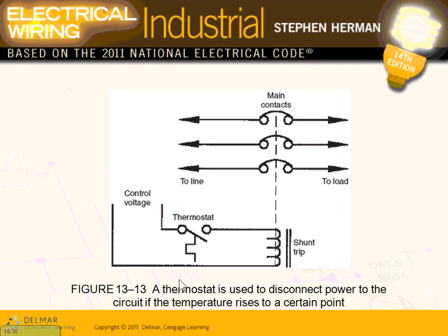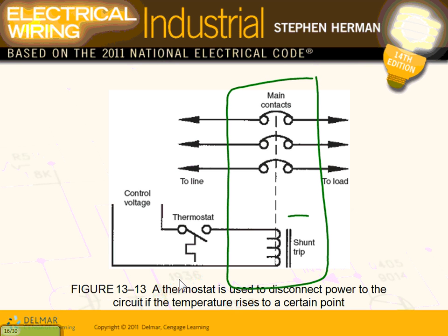Here's what, and I'm going to give you a break in a second, guys. Here's what it looks like, guys. A coil. All these are built into the circuit breaker. You're not doing anything. These are all built into the circuit breakers. So I need a thermostat. If the temperature in this room goes higher than a certain value, say it goes 110 Fahrenheit, I want to make the circuit breaker in this panel trip. I want to turn the power off because I don't want to create a fire, right? So you put a thermostat here, rated 110 for tripping.